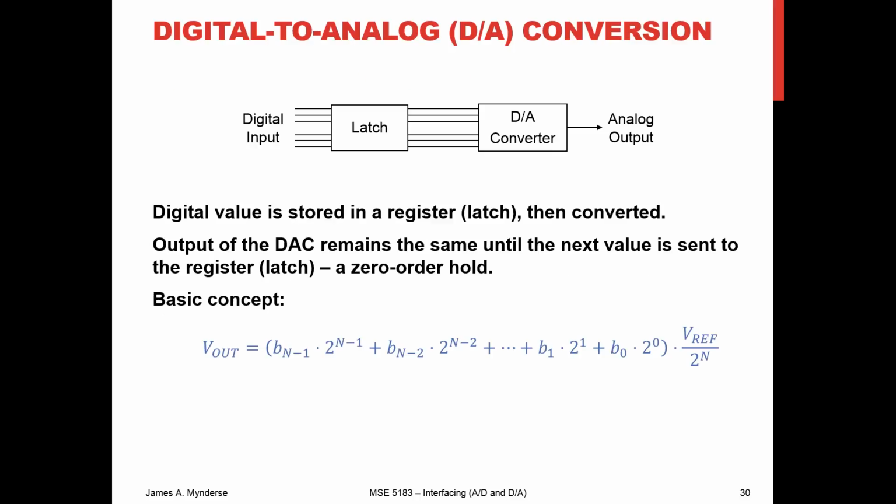So when we are converting from a digital input to an analog output, we're going to take a bunch of digital inputs and we're going to run them all together through a latch. And why would we use a latch? We want to get them all synced up together. Remember we talked about gray code. The reason we talked about gray code was we didn't want values to be changing and have an intermittent bad value. So we're going to do the same sort of thing, except we're going to use a latch this time instead of gray code, because the numbers could be anything rather than just changing one up or one down. So we're going to run them all through a latch. We're going to get them all synced up and then push them all together to the D to A converter so that we have the right number at the D to A converter with no intermediates. And then the D to A converter is going to generate that analog output.